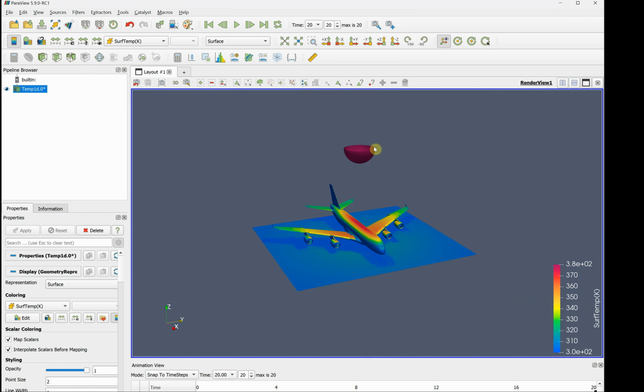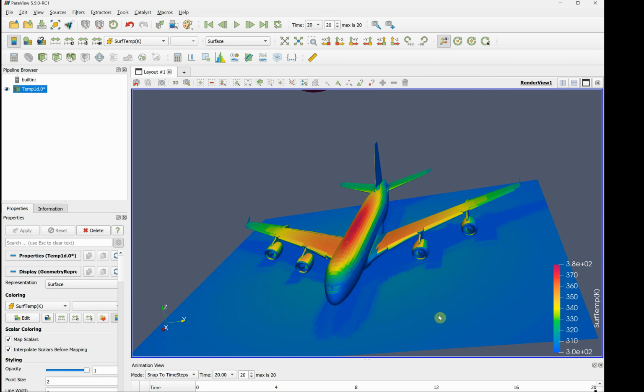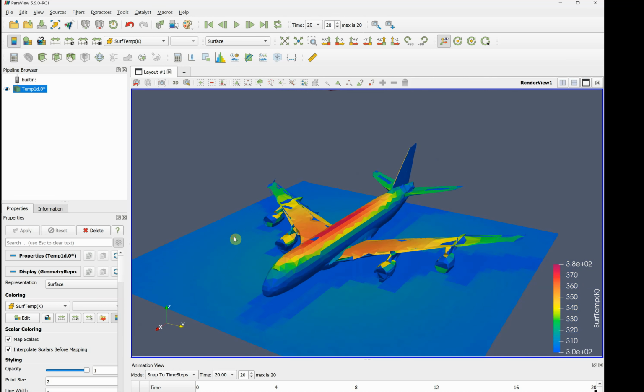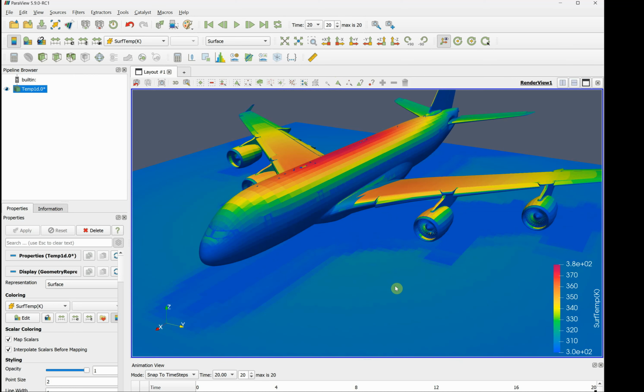We have the hot surface up here, 2500 Kelvin, shining down on this airplane. The top of it's getting hot. This is a 20-second run. It was aluminum, 5 millimeters thick, and it's heated up 80 degrees over that time scale. And you can see that there is shadowing going on. So that's included in the view factor calculation because the sphere up at top cannot see underneath the airplane. So you get the shadowing. The ground is not heating up very much. Looks like maybe 10, 20 degrees.